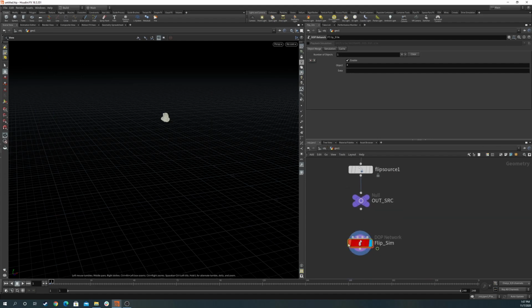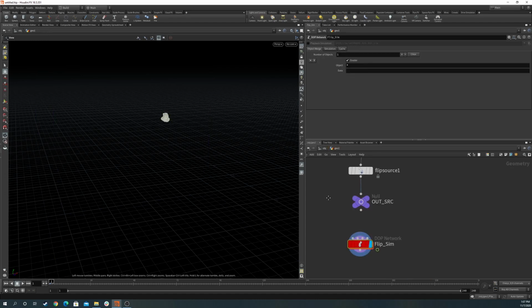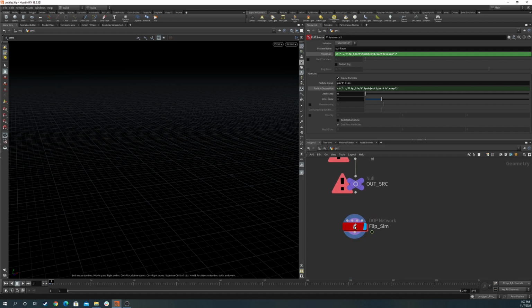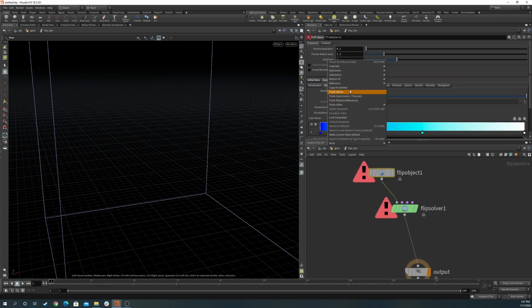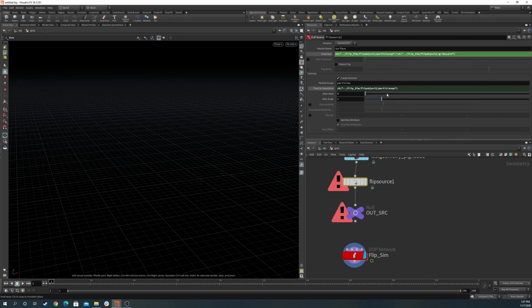It's basically we need to use particle separation multiply grid scale. And these two values multiply together, and that is gonna be the voxel size. So I'm gonna also paste the particle separation in here and multiply this grid scale. And that is the correct voxel size.